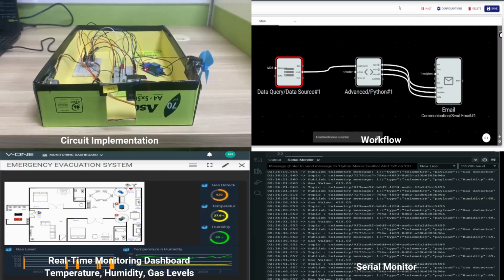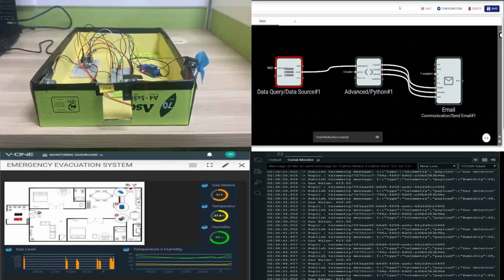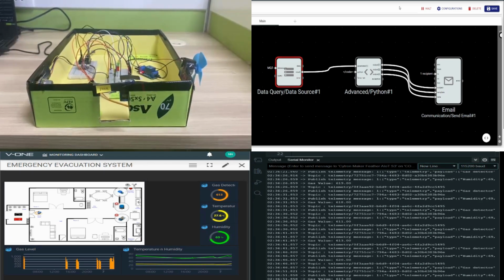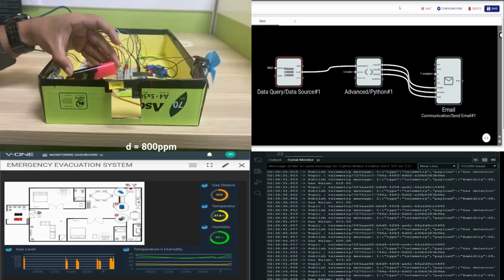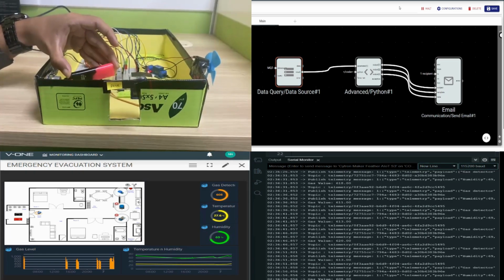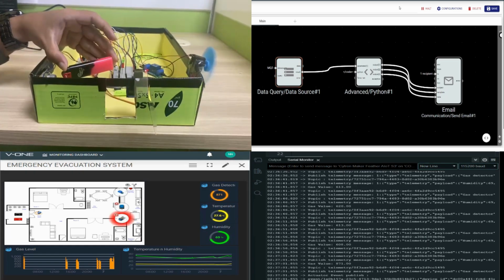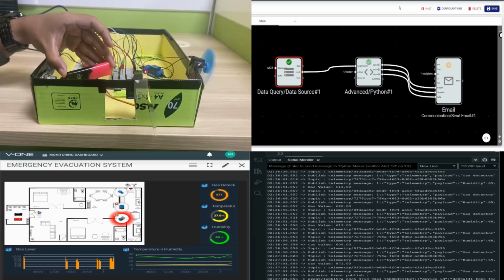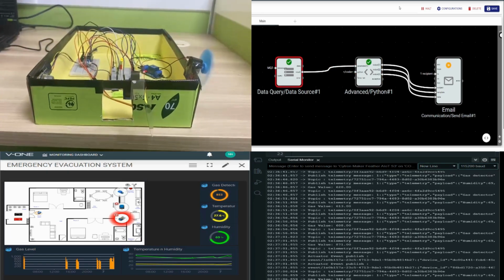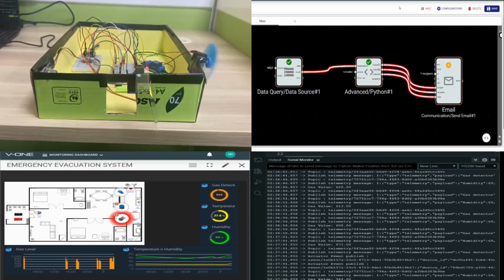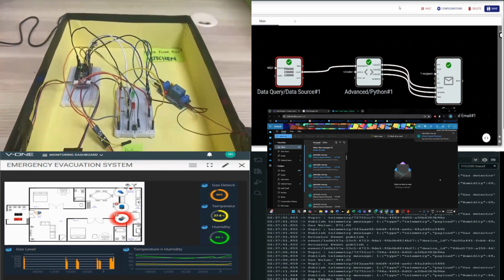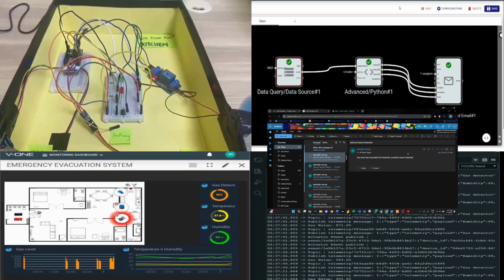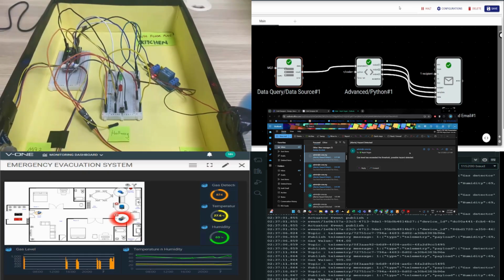Now, as you can see, the panels represent all real-time data collection, and the threshold at 800 ppm for the MQ2 sensor is set as we light up the lighter. The butane gas is being detected, and as you can see, it has reached the threshold of 800 ppm with the actuators activated, which includes the door opening and the exhaust fan turning on. And at this point, we are looking at the LED lights sequentially being displayed and also the email being sent to us.